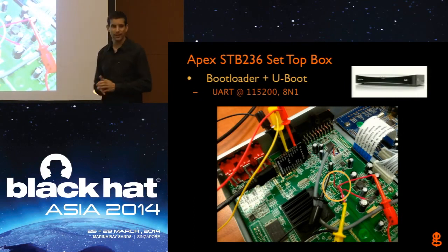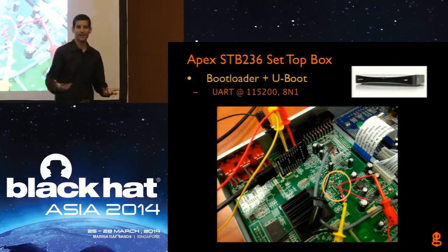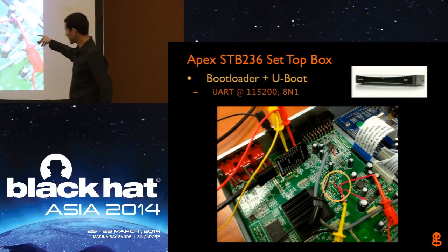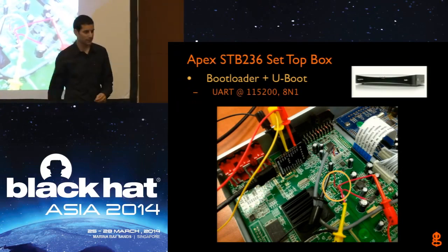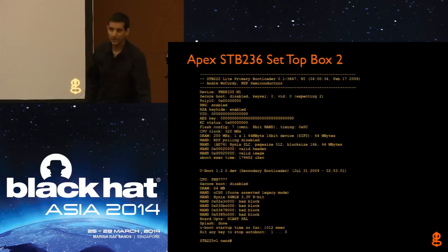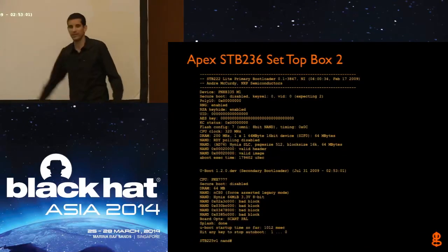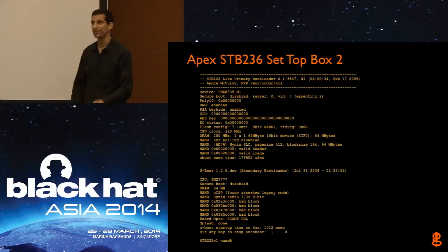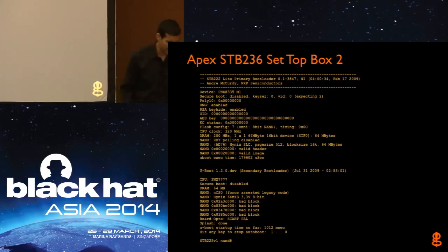Now, if I had the UART detection functionality done on the JTAGulator, we could have just hooked all those test points up to the JTAGulator and had it do it automatically, but we didn't. Once we found the correct pinout, we had to use a level shifter, which had an FTDI part on it, so a USB to serial adapter. Hook that up to a terminal program. We got the baud rate right, and then we can see this boot up screen with U-boot and stuff, which is pretty cool. So that was more of a manual process. I'll show you now how you can do it with the JTAGulator, which is way cooler and requires much less hassle.